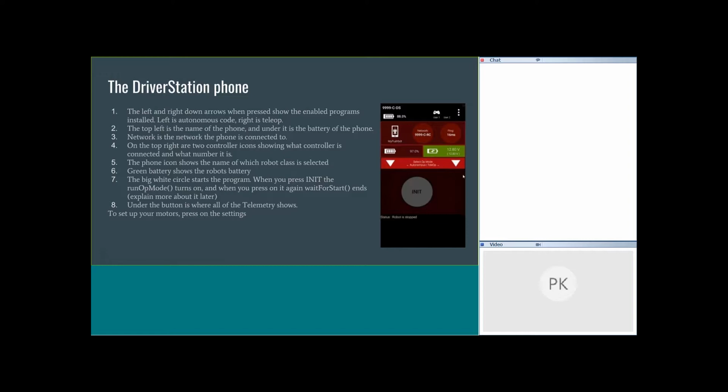It could be that, let's say, the battery has not been charged and then the motors don't spin. It could be that the phone on the robot is off. It could be that you didn't turn on the controllers. It could be a lot of things. And if it's not any of these, you could see, let's say, error messages in this box. This box is very similar to what we did in the first webinar, the print line, the Bakara, as it's called in Hebrew, so it doesn't really help you.